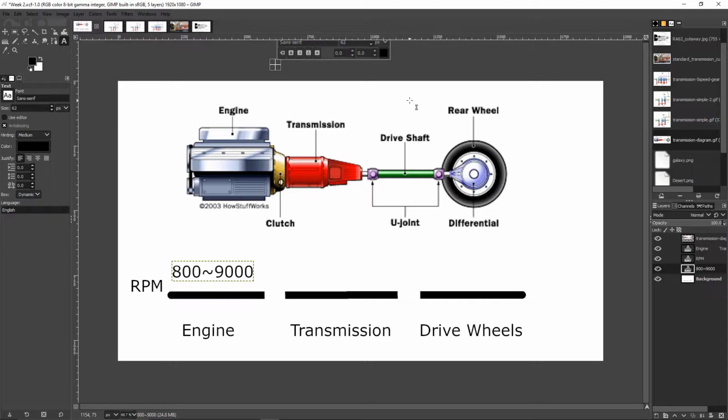When we talk about my sport bike, if I shift incorrectly and dump the clutch, it creates so much engine braking it nearly wants to throw me over the handlebars. In those drag racing videos, we saw the front of the car nosedive and the back wheels come off the ground, and those were all front wheel drive vehicles, so that makes better sense. But we're suddenly now trying to rev the engine up against its want or need or desire, and it doesn't like that. So when that happens, something will snap. Hopefully, and this is a terrible thing, hopefully it's a drive shaft or CV axle that will snap.